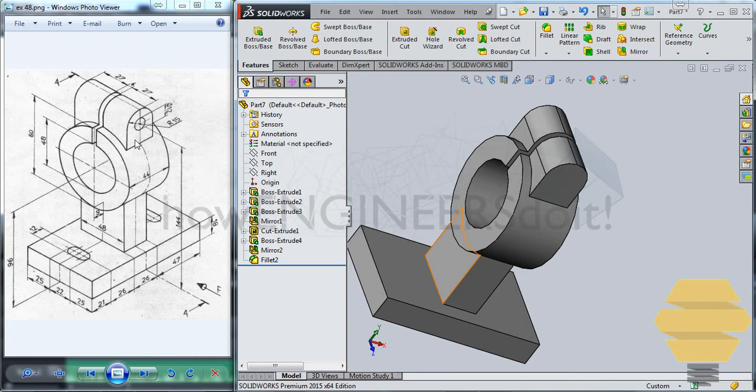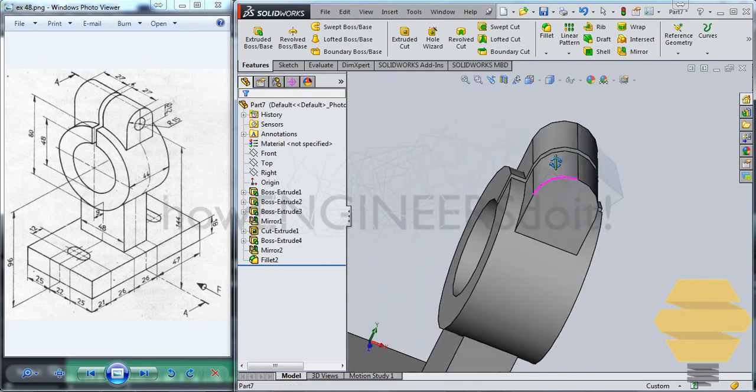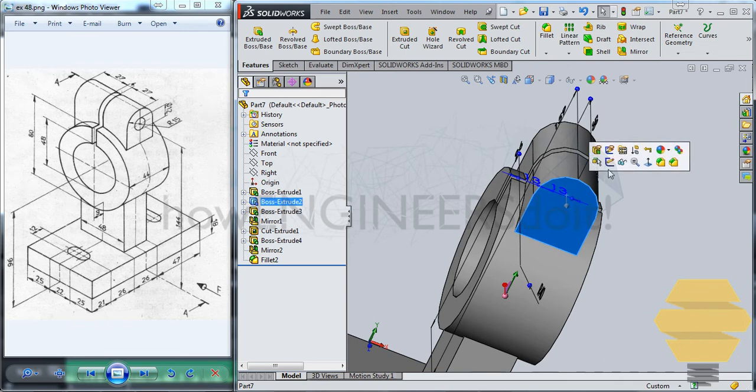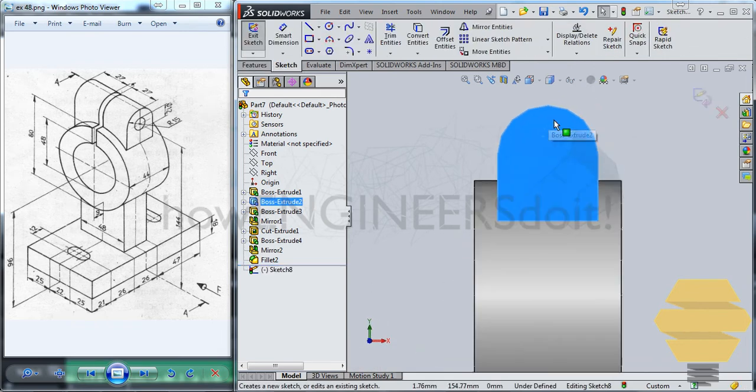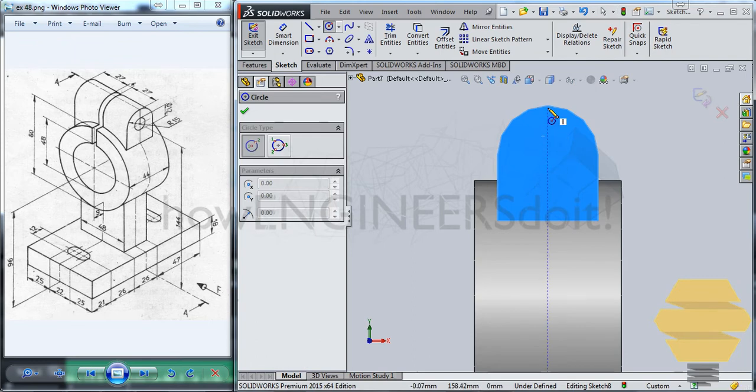This is 26 here and this is 30 here. So if I give a radius 15 fillet on a block of 26 thickness, obviously that will not be a perfect round. So that's the way that I found that. Now anyways, that's fixed, and the reason why I'm explaining this is because it will help you to figure out things when you do the designs down the line.